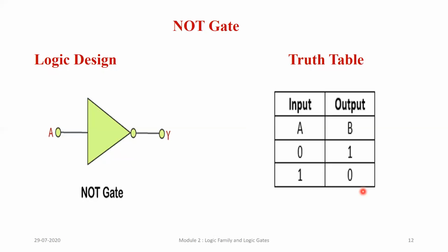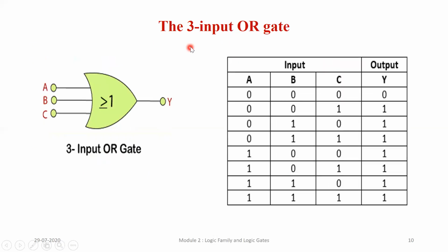The second practical is the realization of NAND and NOR as the universal gates. Realization means using the NAND gate, I will teach you that you have to implement a NOT gate using NAND, and similarly using NOR. Similarly, you will implement an OR gate using NAND, and an OR gate using NOR. So some combinations of circuits are there, and you have to show us the result. So that was the second practical.